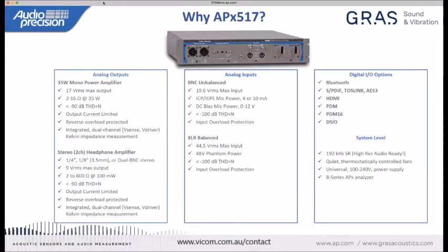And for that, we'll be using specifically one of the BNC analog inputs that can provide CCP, constant current power, for that microphone. On the input side, I realize that this picture shows a Bluetooth module, but what I have physically configured today is a PDM-16 input module, which will let us interface directly to the MEMS microphones.